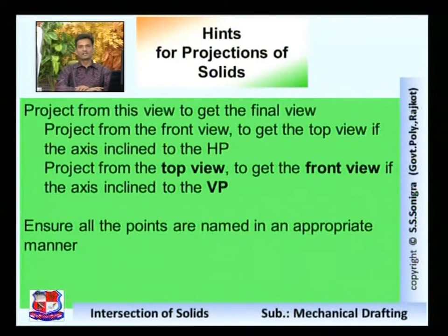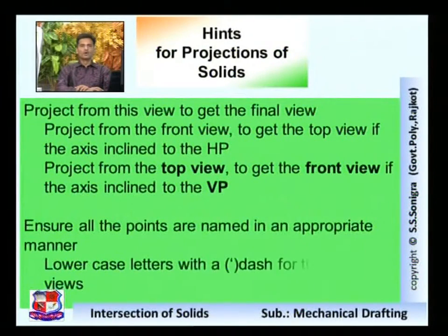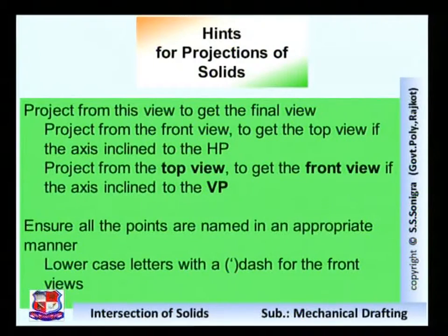Ensure all the points are named in the appropriate manner. You should take care that all the points are given names appropriately: lowercase letters with a dash for the front views, and for the top view, the dash should not be given.